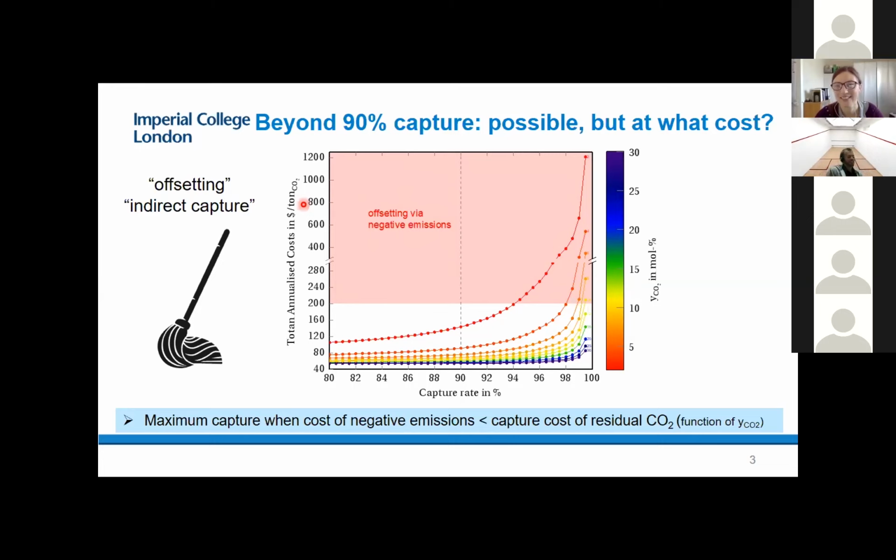If I knew only that answer. What I can tell you is the cost that we're looking at here excludes transport and storage. A widely distributed number is $20 per ton of CO2 for transport and storage. The large-scale projects that are out there in the world that capture CO2 from either a hydrogen plant or a power plant are around $40 to $60 per ton of CO2. So I would see a cost decrease getting down to maybe $20, $30 per ton of CO2, and there's also the long-term target for solvent-based technologies at least.